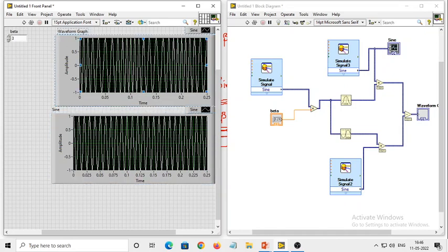Now you can see there is an increase and decrease of frequencies, which is the basic principle of FM signal, where you will be having Fmax and Fmin, and also this increase and decrease of frequencies is with respect to the message signal. Whenever the message amplitude is high, you will be having Fmax. Whenever the message amplitude is less, you will be having Fmin. So such type of variation in frequency is observed in FM signal, and you can clearly see such variation in the graph. Okay,